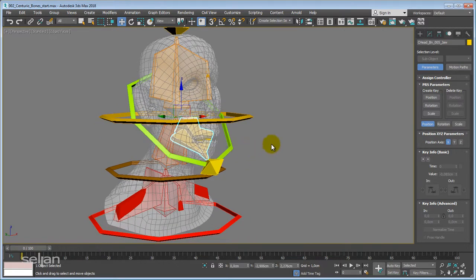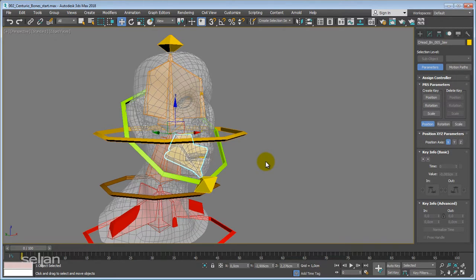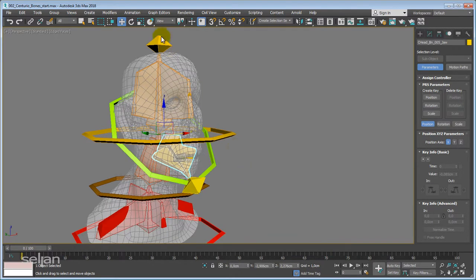Now, before we do this, one thing that we have to take care of is pivot points. I will just quickly create this orientation constraint to check what happens. Alright, you see the flipping caused by an orientation issue, and we will handle that, but let me first try to make this connection.